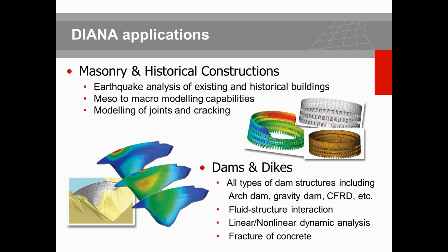DIANA also is very well known for simulation of masonry and historical structures. Any masonry structures or historical buildings which are subjected to earthquake can be modeled in DIANA, based on dedicated material models and different techniques that we have. These models can be simulated at two levels, either meso or macro. So literally you can model everything as a continuum model, or you can model them based on the individual bricks